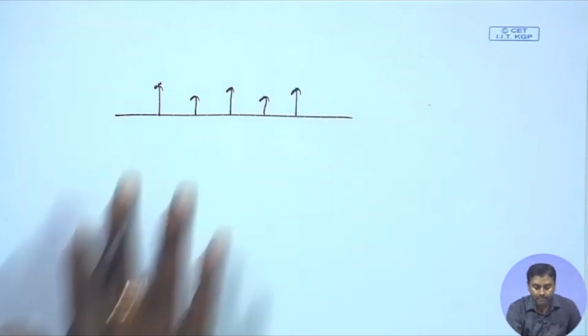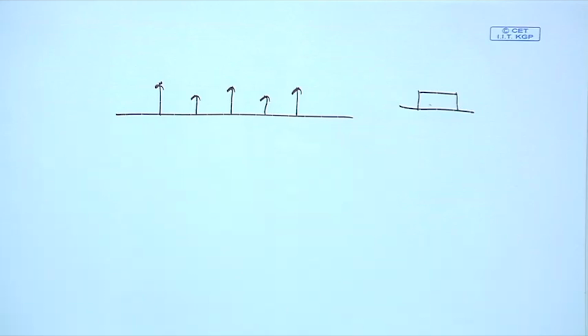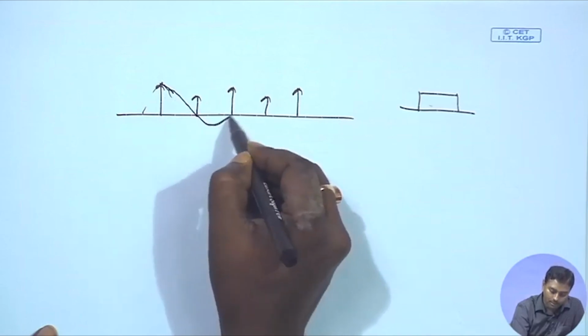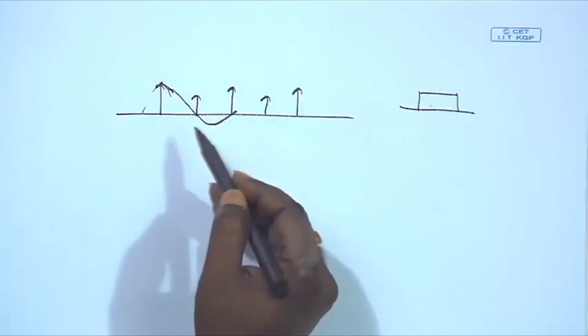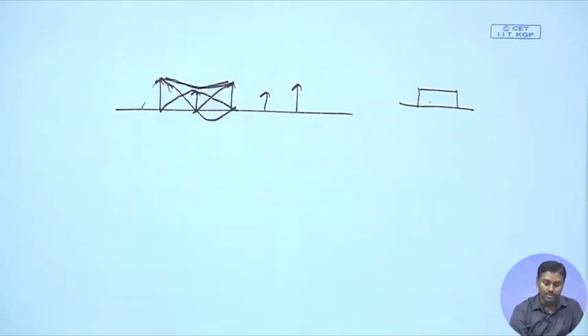Suppose I now have just the samples. Whenever we say we pass it through a low pass filter, the transfer function is basically a box function. So, what will be the corresponding inverse Fourier transform? That should be a sinc function. If these impulses pass through this impulse response, there should be a convolution, and everywhere a sinc function will sit one on top of another, and we have also proven that the zeros are exactly over the other samples. If at every sample you put the corresponding sinc function with this amplitude, you will see those sinc functions getting added will create the original message signal.